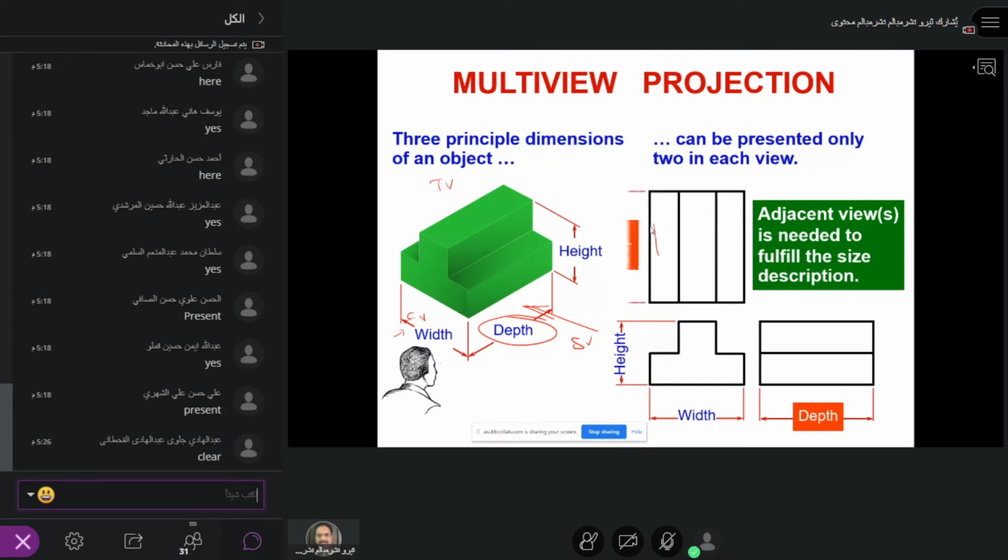Okay, so this will give you an idea for any engineer. Trained engineers, when they see the multi-view drawing, they can visualize it, combine it together and come up with an idea: okay, this is how this shape looks if I see it in a perspective drawing or even in the projected drawing, orthogonal projection, orthographic projection. They provide you at least 3 views: the front, top, and side views.